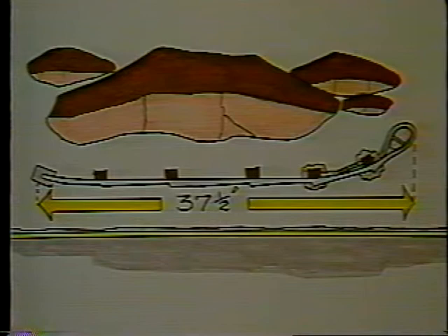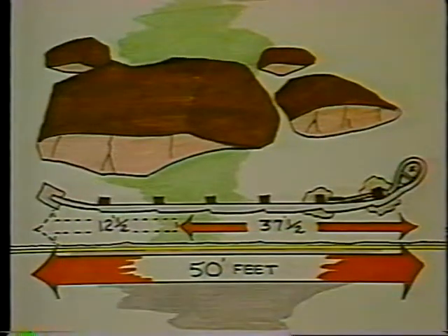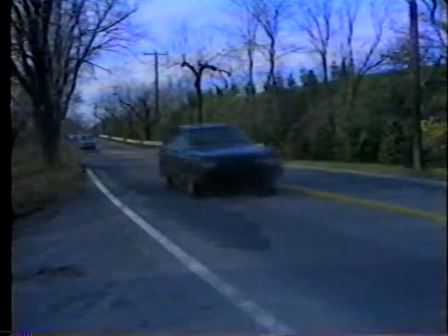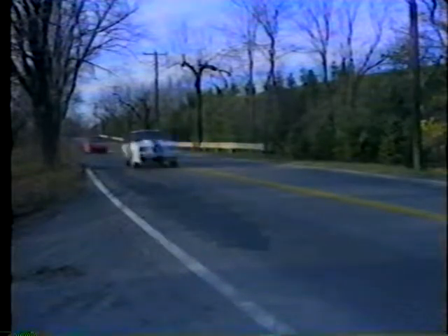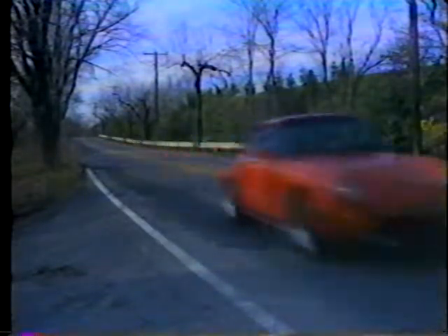Length of the BCT is also a critical factor in its reducing injuries and deaths when hit. Recommended length is 37.5 feet. Some agencies have extended the terminal length to 50 feet, anticipating the extra length will offer more energy absorption capacity. However, since the BCT is intended to divert an impacting vehicle to one side of the barrier rather than absorbing its kinetic energy, the extra length provides no added capability.